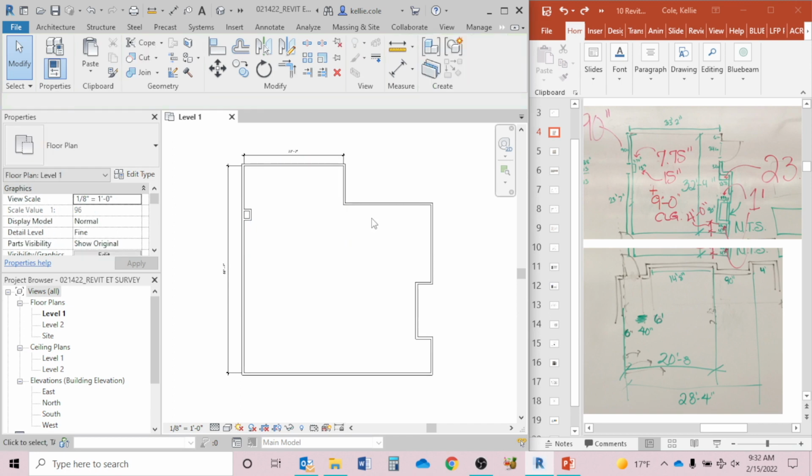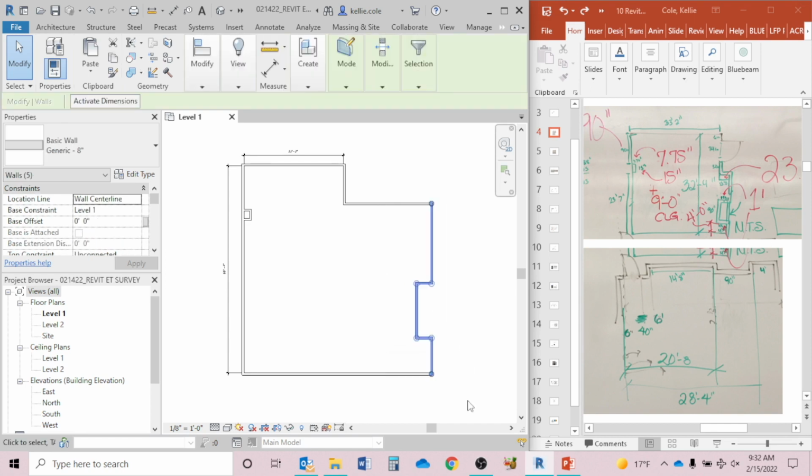If I want to make it just a bit smaller before I do my other dimensions, I'm going to select this whole series of walls. To select just the walls within the rectangle, I'm going to hover my cursor upper right, click, drag left, let go of the cursor. I can touch a wall, hold the cursor in, and just move my hand.